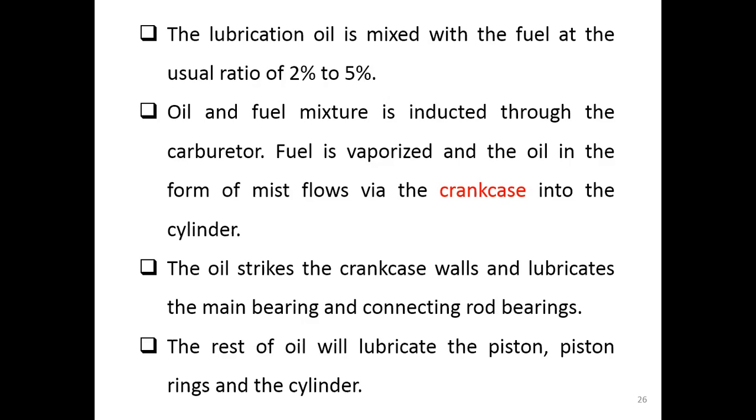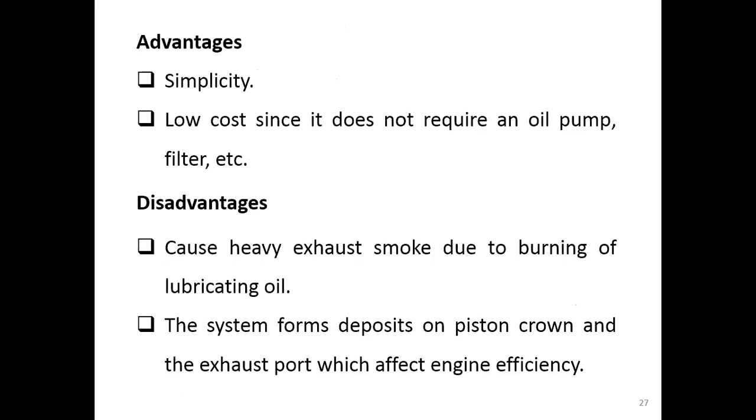The other portion of the oil will also go to lubricate the piston ring and the cylinders. The advantage of this system is what? It's simple. Simplicity. It's very simple, and it also has a low cost because it does not require what? An oil pump, an oil filter, and others. So you don't need anything, and the system is very, very low cost.